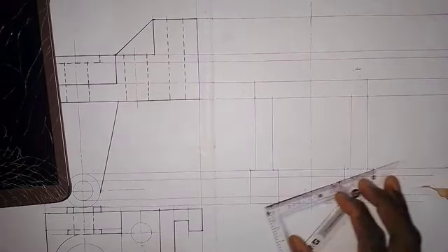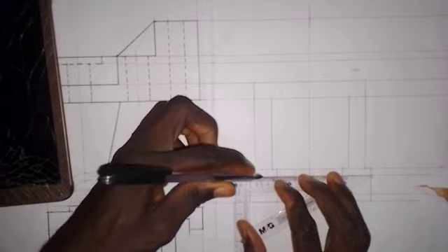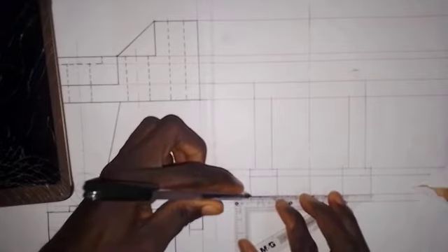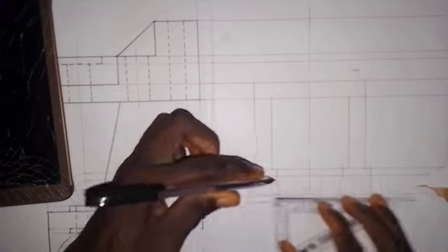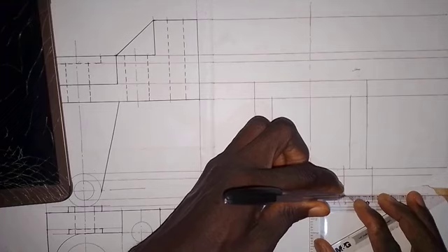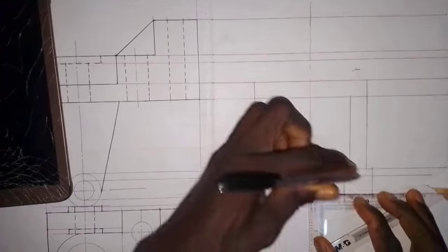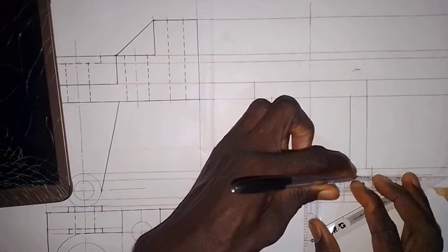Okay, so then the hole inside this will be drawn with short dashes line. So we draw a short dashes line. So I'll do the same thing here. So we draw with short dashes line. It is hidden from us in that end elevation. Okay, and don't forget that this is the left end elevation. So looking at the whole of the object. So this is left end elevation.